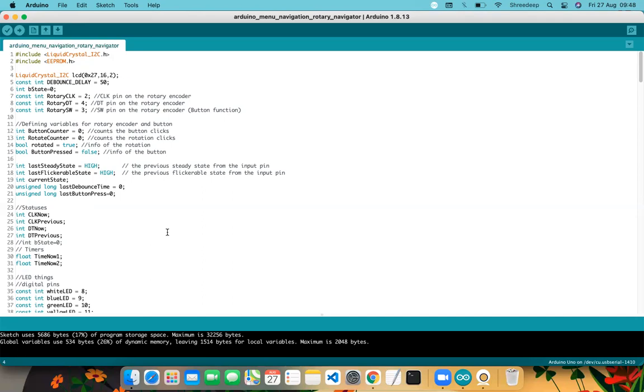Because the things are happening not in the loop but in the interrupt driven program, it's some basic information to let the Arduino program control know that this is happening. Void loop does not know what is happening inside the interrupt driven program. It does not call the program itself; it runs all the statements written inside the void loop sequentially.